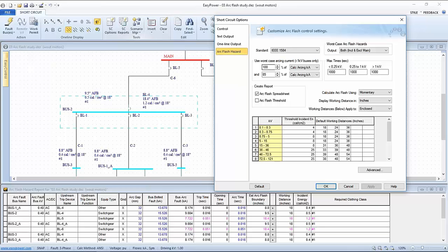All right, in terms of the 100% versus 85%, that's a recommended comparison to be made, but these can be adjusted for whatever reason if our engineering staff wants to consider different points to do a comparison. And the reason is here, because the slope of the protective device, the curve on the protective device may vary, the lower current could actually produce a higher incident energy, and then again that's being reported on my arc flash hazard spreadsheet.